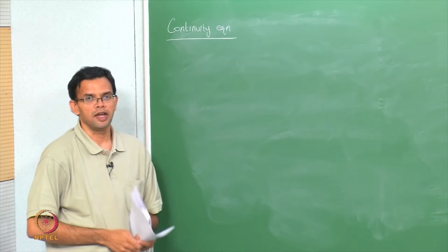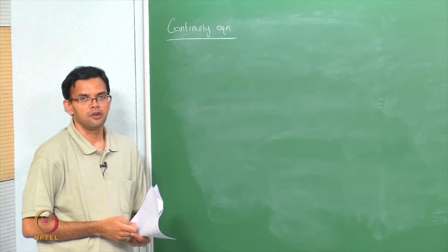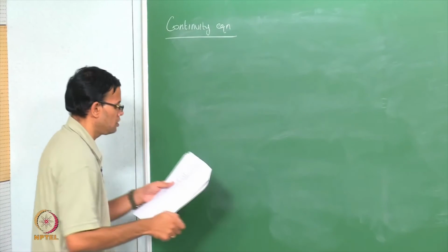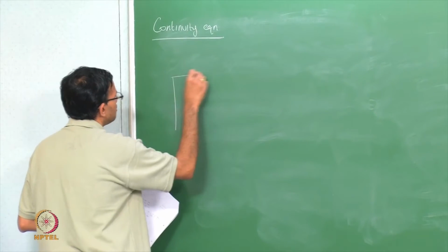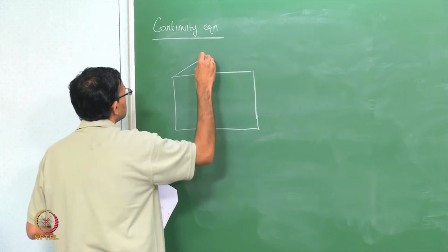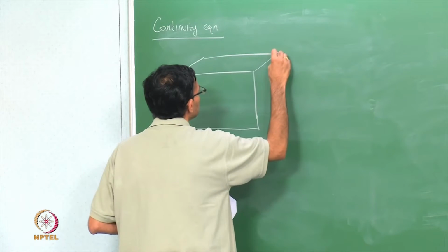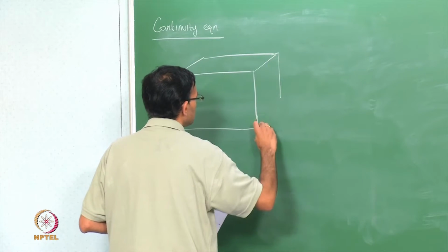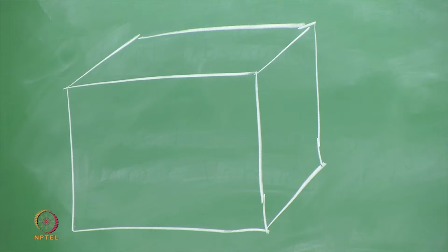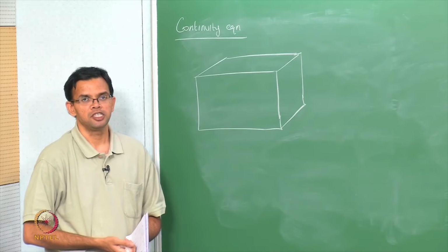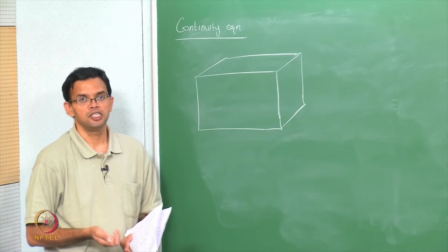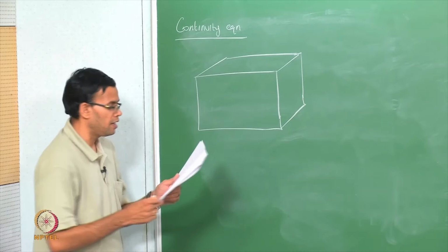Here we want to write a generalized equation for the interaction of the light with matter and how it generates electrons and holes. So, consider the case of a slab. Again, for simplicity, we are going to deal with an n-type material under weak illumination, so that we can ignore the change in the majority carriers. The only significant change will be in the minority carriers.